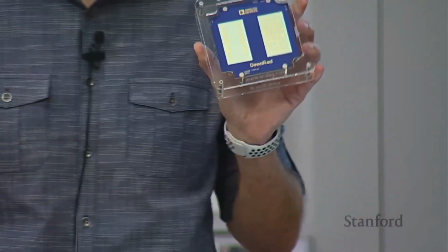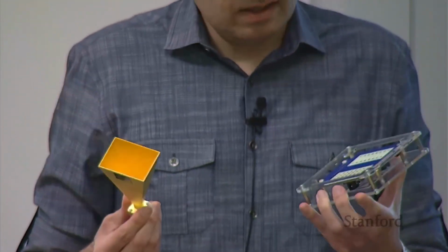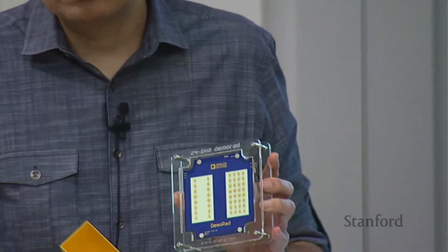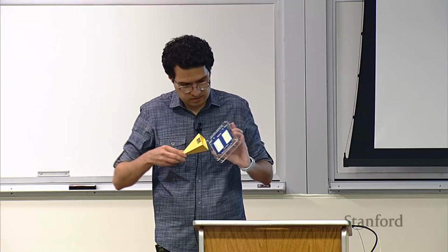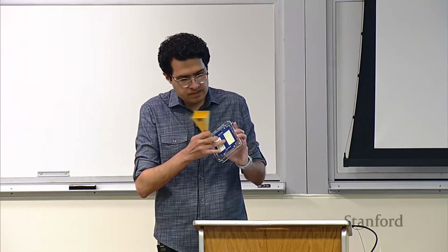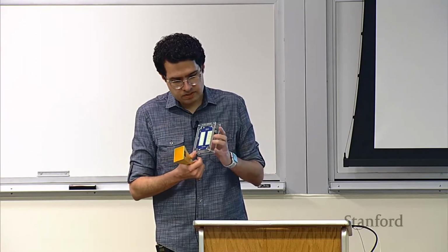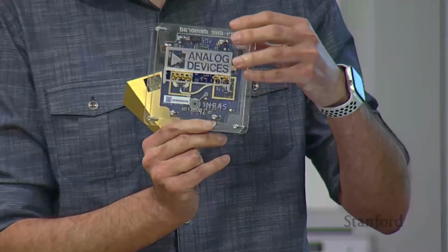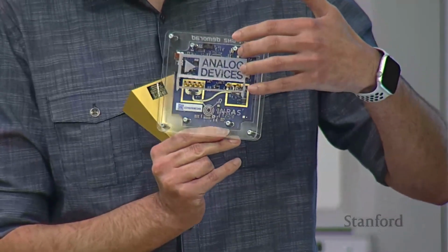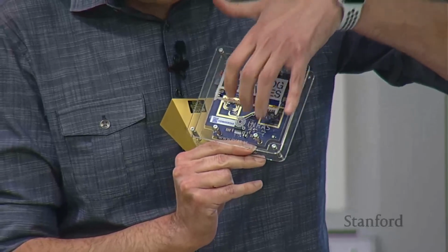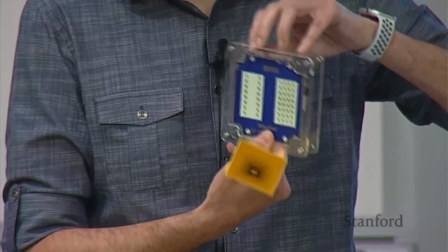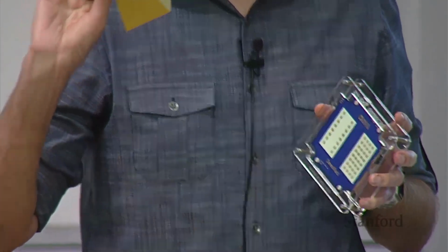That's because these are for the same frequency, and the dimensions of your antenna have very specific relationships to the wavelength, so that's why these are roughly the same. This one, the microstrip, it's not just an antenna. On that same PCB, if you look at the back of it, you have your full radar circuit. You have the transmitter, there's a DSP chip here, there's everything. So it's the full radar system, versus this one is just an antenna.